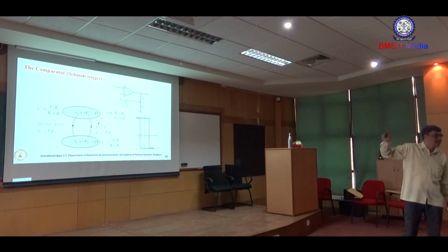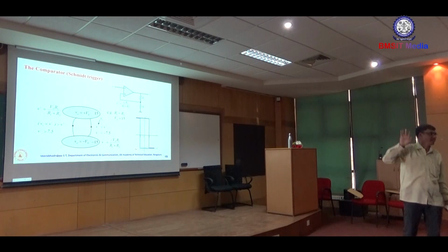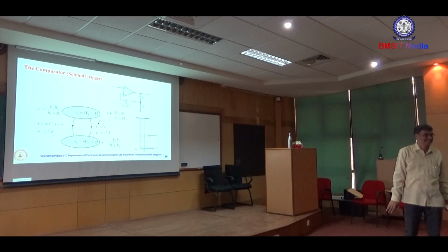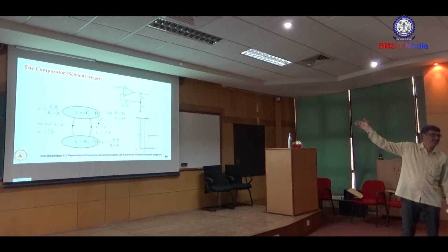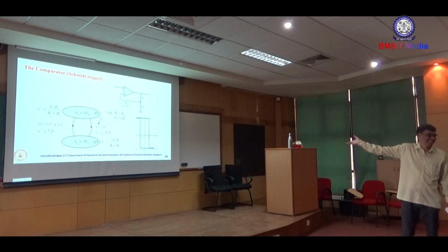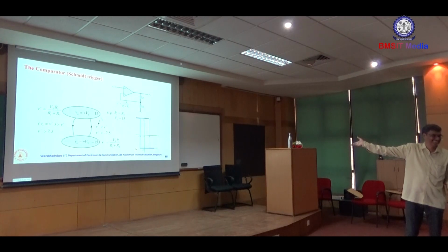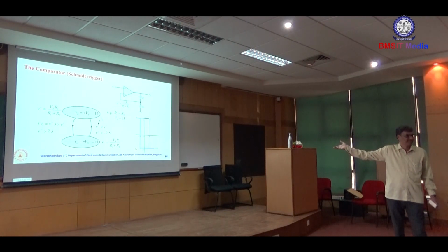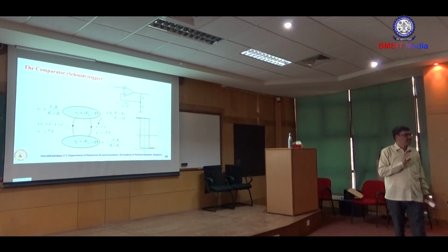The only thing is, identical transistors are used in your operational amplifier if they are working properly. But from your experience in the laboratory, you never get identical. Positive saturation is about 10, 12 volts, 11 volts, so negative saturation is going to be 10 volts. But the industry standards say they are exactly symmetrical.